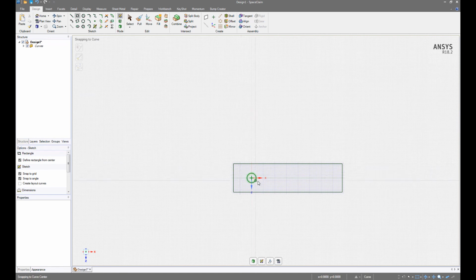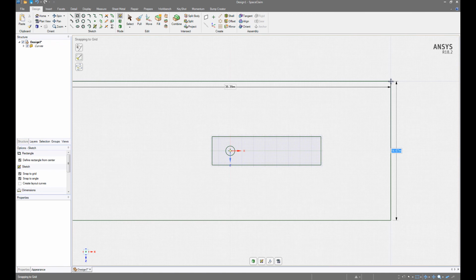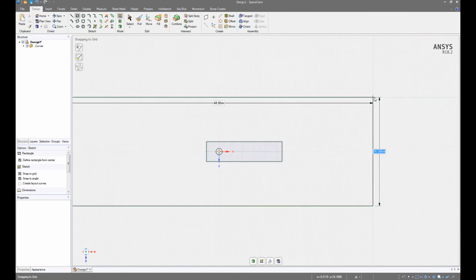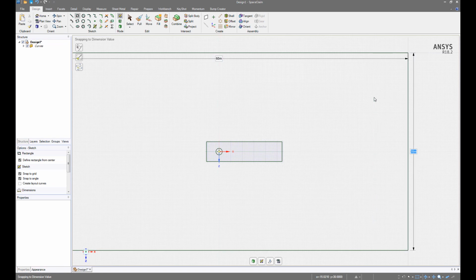The reason we create two domains is to reduce the mesh size so that the simulation runs quickly. The inner domain will be meshed finely, and this allows us to capture accurate physics inside and near the cylinder. The outer domain is meshed with a coarse mesh. This allows us to reduce the mesh count while still maintaining the validity of our boundary condition assumptions.